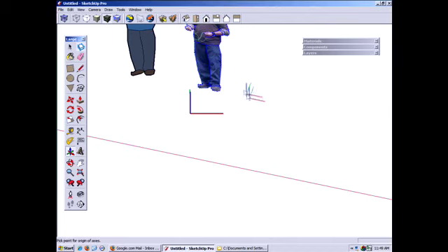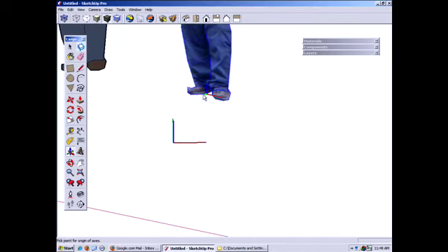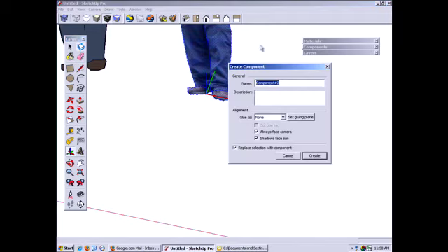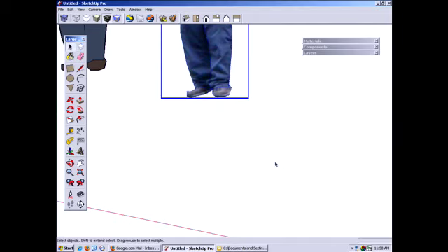So I'm going to set the gluing plane at these feet. Click once to plant it, and now you see I'm setting the red direction. And here's my red axis of the entire model. I just want to line those up. So right there, red axis, click once. And now as I move back, mostly I just want to make sure that blue axis is up. If it's up, then I'm safe. So click again. My axis is set correctly, and create that.